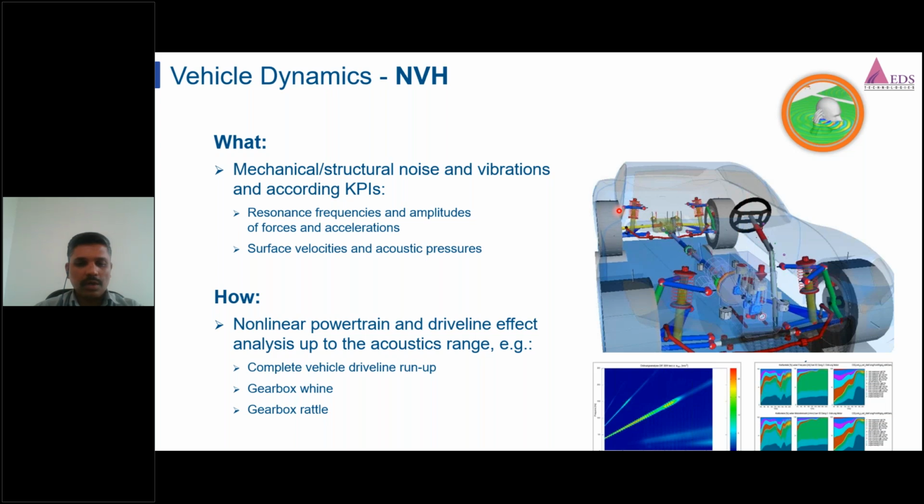For instance, by doing a complete vehicle driveline run-up simulation. So what is this? It is a diagnostic procedure used to assess the condition and performance of the vehicle's entire driveline system. This test involves running the vehicle through various speeds and loads while monitoring the driveline components for any signs of issues.